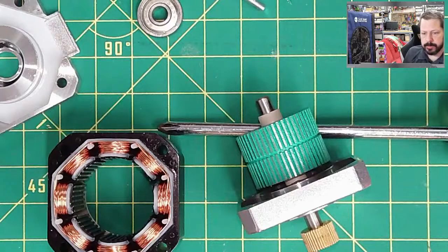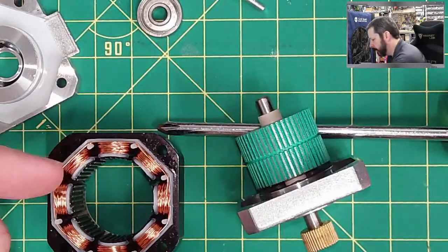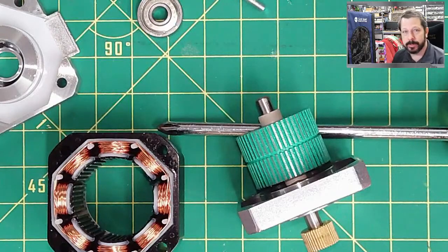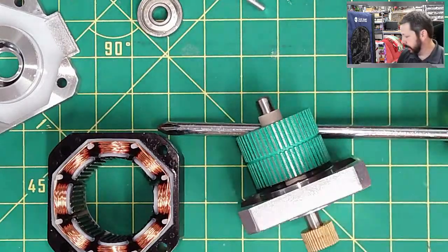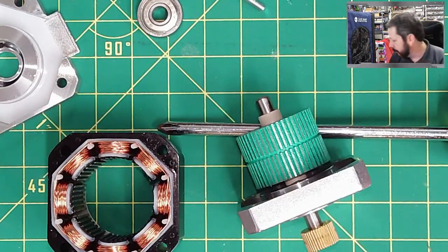You might have heard of the term microstepping. What that means is that instead of fully energizing sets of coils, you can partially energize sets of coils and kind of get the stepper motor, the rotor in here, to exist between steps. So with half stepping, you can be halfway between steps. Quarter stepping, you can be a fourth of the way between steps, and I think some of them can go down to 1/256 stepping. So they can get very tiny micro steps.